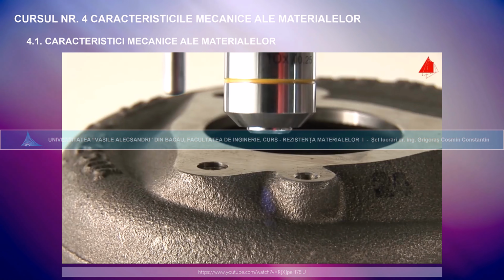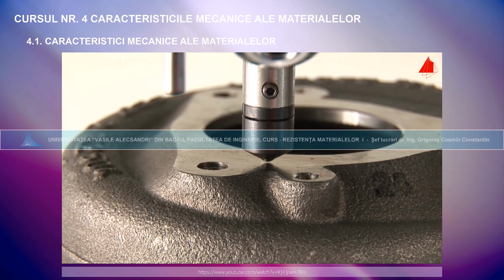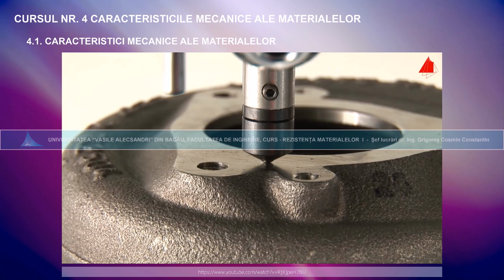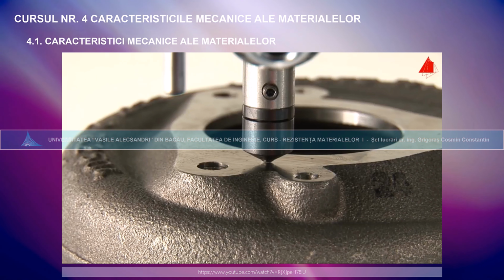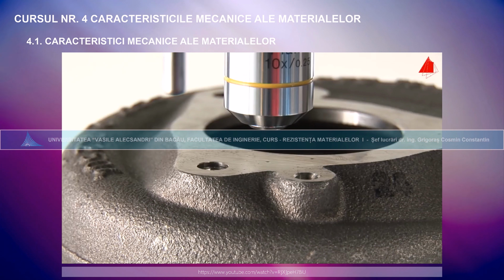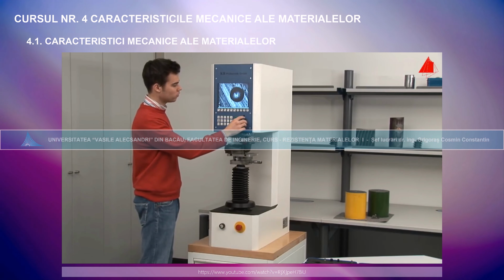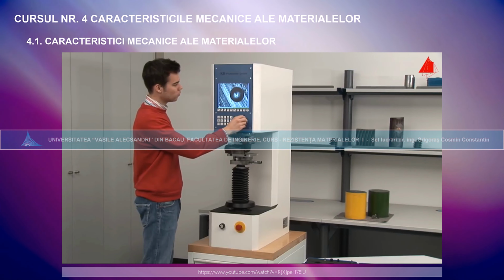The testing machine rotates the lens back to its resting position and places the spherical indenter carefully on the test piece surface. Gradually and shock-free, the test force rises to its specified value. After maintaining the test force for a certain time, the indenter automatically lifts off again and the microscope lens pans back to its former position. The indentation can now clearly be seen on the monitor.